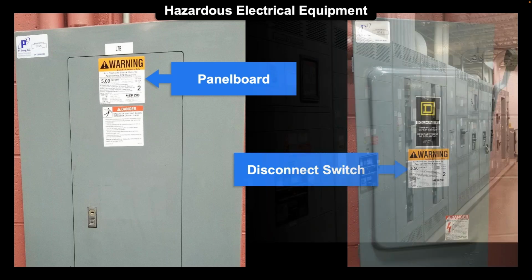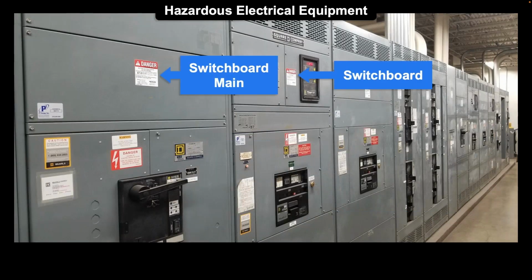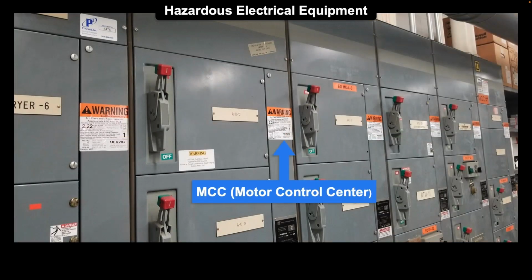Switchboards, you'll have a label for the main, and a label for each section following. Switchboard, switchgear, any equipment that has this kind of setup. MCCs, you have a label for each section, whether you're going to see it on the wire run trays here or at the top of each section of MCC. It's going to be the same label across each section. Same bus run down the back, same potential for each bucket.